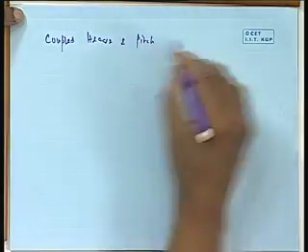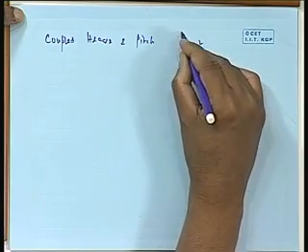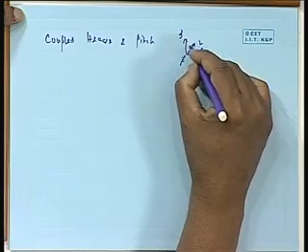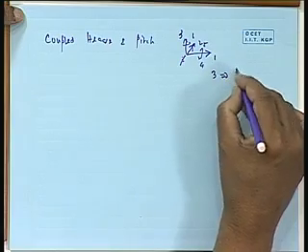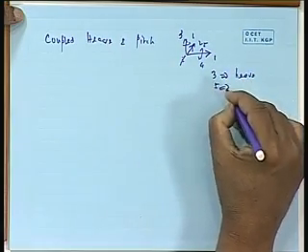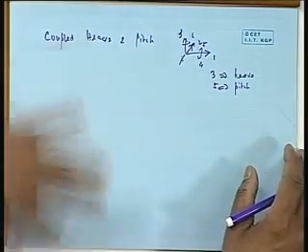Now, we are calling this the axis system: this is 1, this is 2, this is 3, this is 4, this is 5, this is 6. So index-wise, 3 is heave, 5 is pitch. It is a convenient thing to write the motions in index form: x, y, z, and moments about x, y, z. You can call it x1, x2, x3, and rotations about the axes as x4, x5, x6. So index-wise, x1 is my surge, x2 is my sway, like that. So coupled heave and pitch is then 3 and 5.